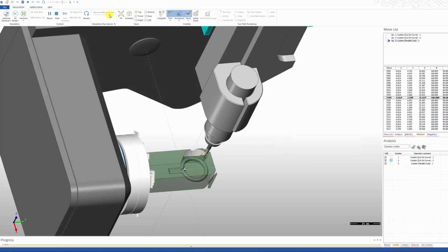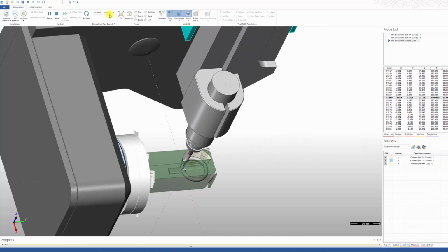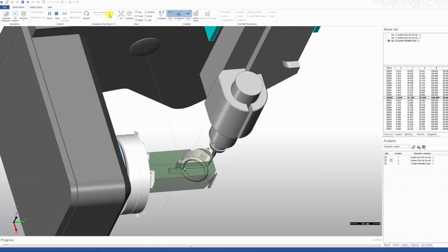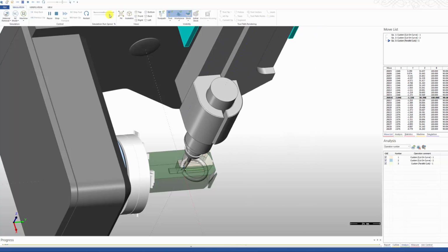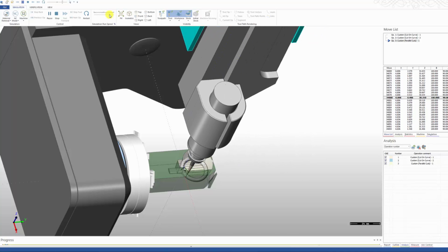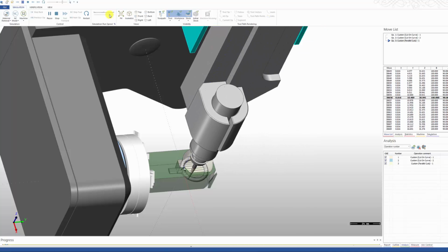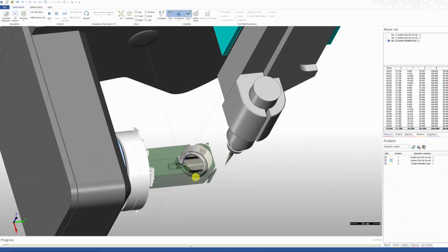And you can see that it's going in a Y direction, and even though we specified the boundary curves just slightly overlapping a ring, it's still cutting the inside. And the reason for that is because, of course, it has to move the bit to the next point. So when it finishes here, it has to go here, so it traverses here. And what that means is that we end up cutting out this entire area.